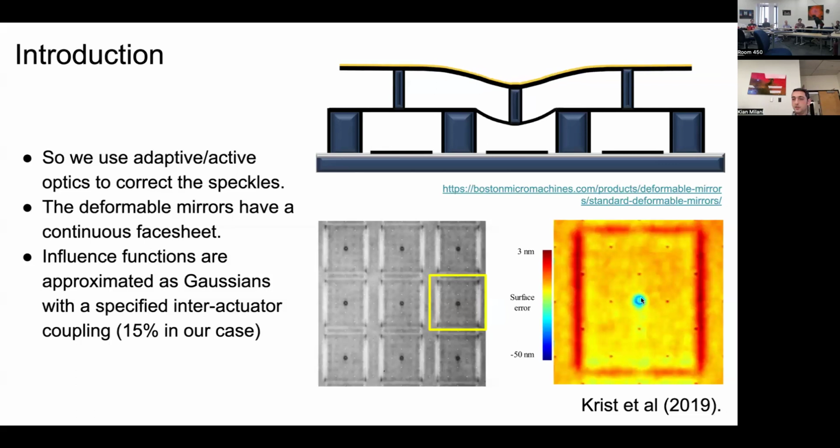This is an actual depression in the DM, this little spot in the middle where the post behind one actuator is. And then these tiny things here, those are just holes used for the etching process of the DM. I think they're about 2 microns or somewhere between 2 to 10 microns in diameter. I don't remember what John Krist quoted in his paper, but yeah.